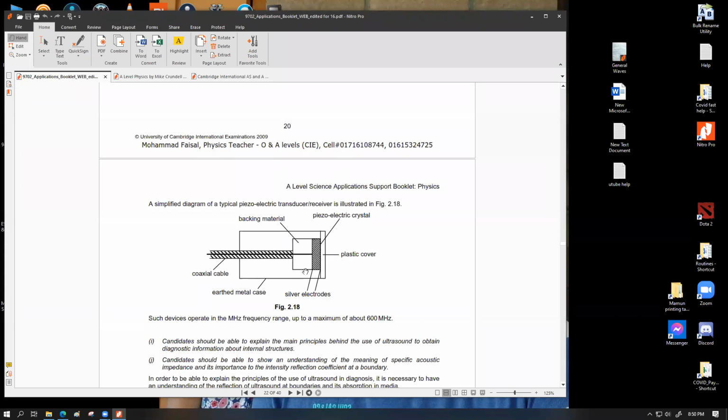Reflections from different locations inside the body are going to reach the same piezoelectric crystal after different times. Depending upon how much time has passed for receiving each of these reflections and how strong those reflections are, we can actually predict what is in front of this object. This is basically how a sonar works. Sonar means sound used for navigation, the mechanism by which dolphins move around or submarines work. So this is basically a linear view of how the sonar works.